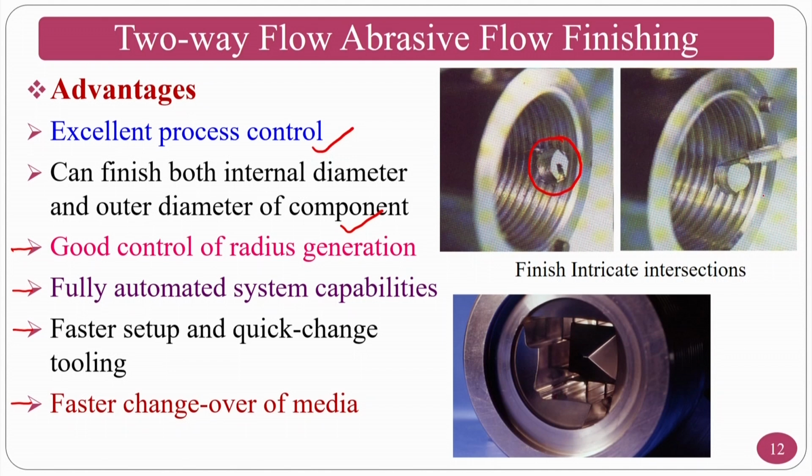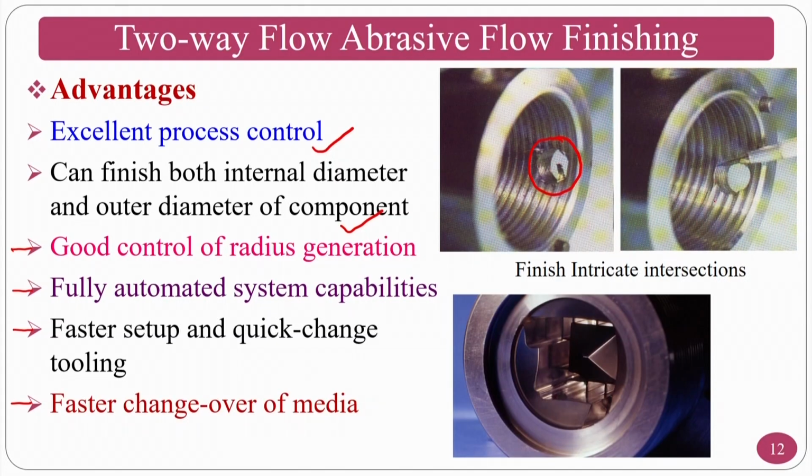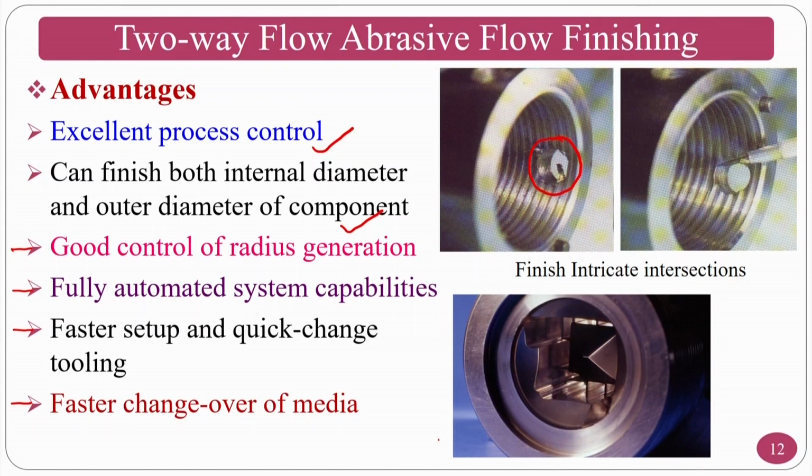However, this deburring can also be done by thermal-based deburring processes. For that purpose, if one has to go for this type of deburring process, you have to have proper tooling. The bottom one can be finished by the abrasive flow finishing process. However, for the top one, people normally prefer thermal-oriented finishing processes for deburring applications, and you have every chance to use the abrasive flow finishing process also if you can maintain the proper tooling.